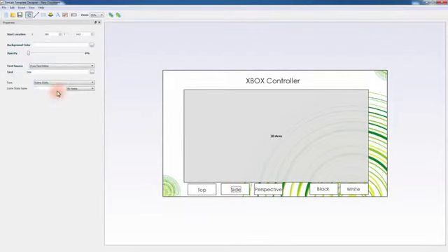Once you're done, go to File and select Save. Set the name and path of the template and click Save. Close the Template Designer and go back to SimLab Composer. Click Refresh, then select the template you have just created.